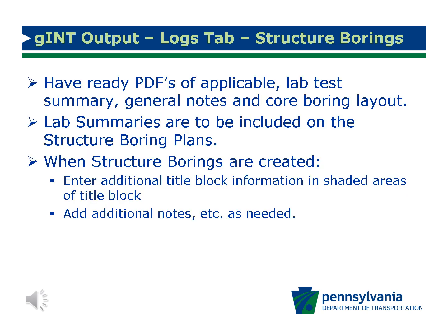Users are to create individual PDFs of applicable lab test summaries with the borings corresponding to the structure plans. That is, the lab test summary reports include information only from the borings corresponding to the structure and structure plans. The pertinent boring logs may be selected manually or filtered via the Output tab to use only the borings applicable for the specific structure plans and structure boring logs.